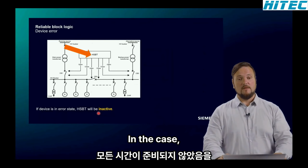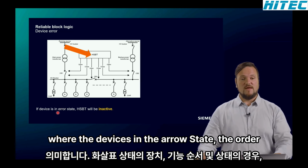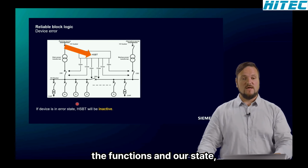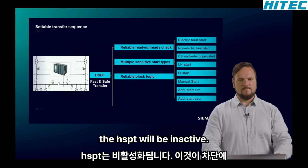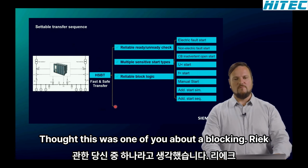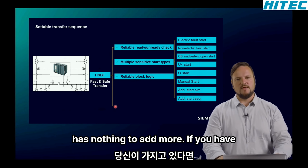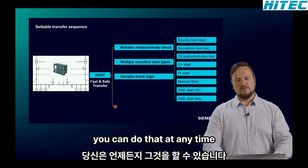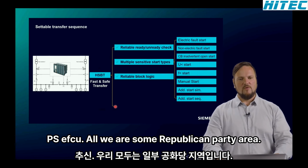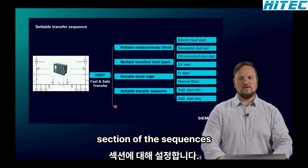Or in the very seldom case where the device is in an error state or the function is in an error state, the HSBT will be inactive. So this was one overview about the blocking logic, which is already implemented. That means from your side, there's nothing to add more. If you have some specific applications, you can do that at any time via CFC or via some additional blocking criteria. So then we come to the settable transfer sequences.